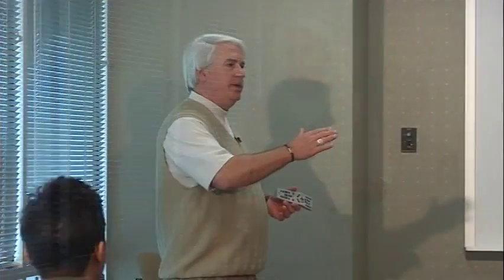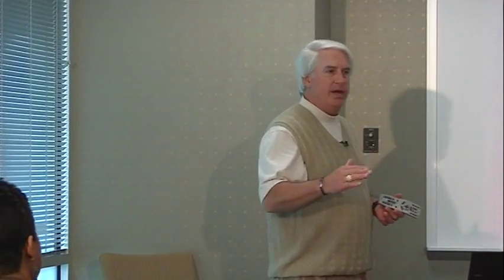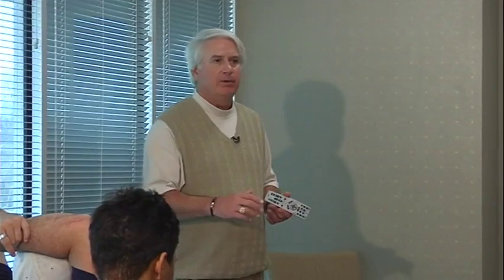Most of the people that have automatic tank gauges set them up to run this test like 5 days a week at like 7 o'clock in the morning, when you've got some quiet time at your tank. So these things generally run these tests sometime early in the morning when the tank is as quiet as it's going to be during the day. And then you're going to get an accurate volume reading of the product that you have inside your tank.